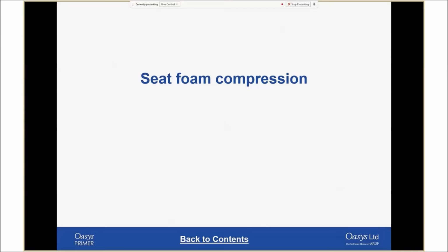So let's say you've positioned a seat, and you've also positioned your dummy in the seat. What you're likely to have is the dummy penetrating into the seat model, because your seat foam is not compressed at all and your dummy is positioned at the correct H point. So the next stage would be that you'd want to depenetrate the occupant from the seat by squashing the foam.